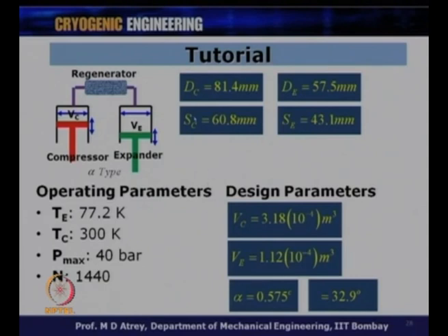So here you have to take a call, how many iterations would you like to do? Is Pmax equal to 40 bar enough? If not, can it be higher? If it is on a higher side, these dimensions can still be reduced, because comparatively for a given Pmax my Vc or Ve will get reduced for higher pressures, and therefore this can be considered on a lower side.